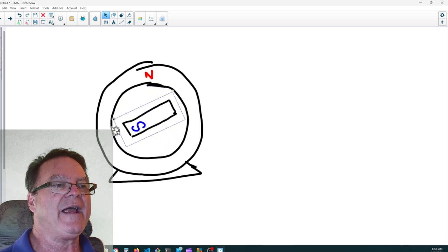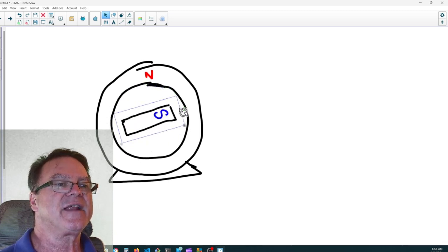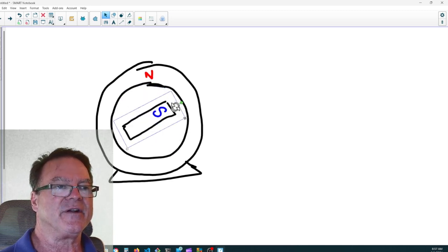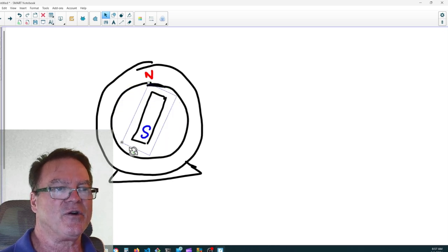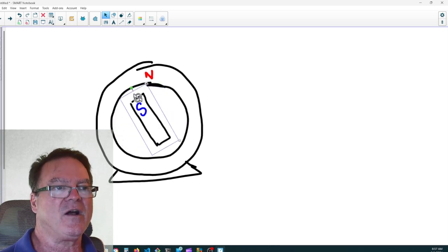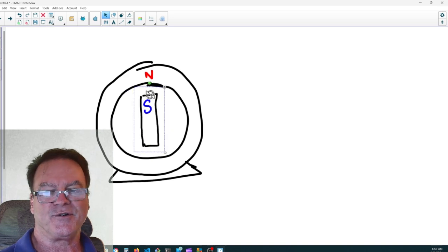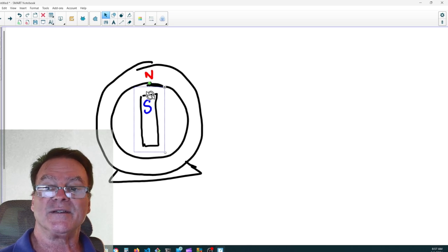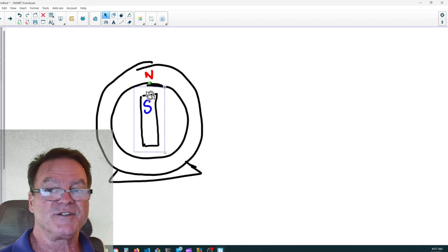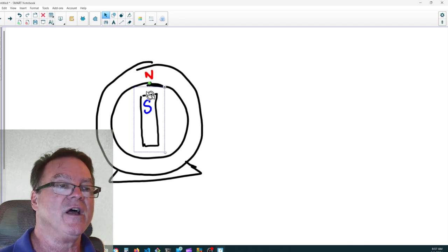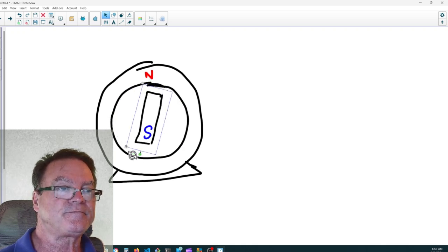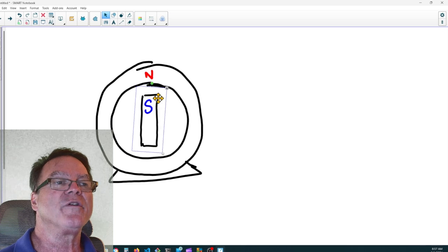That south pole will hang with that north pole because it has a separate, they call it an exciter. You use an exciter, it's a DC generator, and it generates a DC current through this rotor that causes it to have, I want to use the term permanent, but it's not a permanent magnet. It has a south pole that remains a south pole. Doesn't have a commutator, doesn't change. That south pole is always south. So it follows that north, and it follows it at synchronous speed. That's the only motor that turns at synchronous speed, is the synchronous motor.